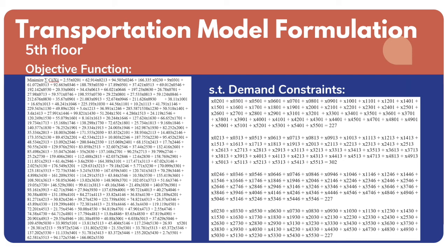Now, the capacity of the exit stairs was obtained from measuring the flight of stairs and its width, where an average of 4 or 3 people could occupy each step of the stairs itself. With the mentioned properties, the researchers then computed the capacity of each stairs, which is the ratio of its capacity size per flight to the total capacity size per flight of all stairs, multiplied by the total number of occupants on that floor.